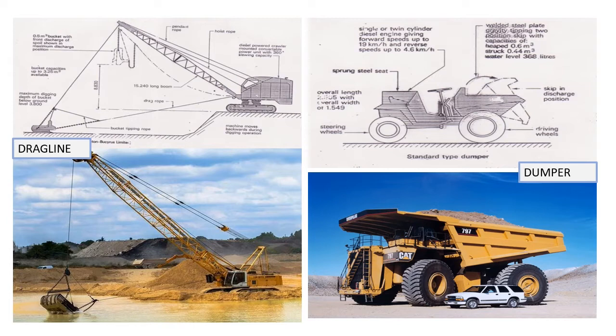Next, we have dumper. These are used for the horizontal transportation of materials on and off construction sites, generally by means of integral tipping skip. Highway dumpers are a similar but larger design and can be used to carry material such as excavated spoil along the roads. A wide range of dumpers are available of various carrying capacities and options for gravity or hydraulic discharge control with front tipping, side tipping or elevated tipping facilities.